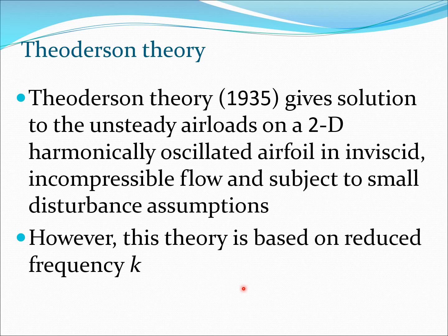Now, Theodorsen's theory is one of the main theories used as far as fixed wing problems are concerned. And this theory gives solution of the unsteady loads for a 2D harmonically oscillated airfoil in inviscid incompressible flow and subject to small disturbance. So this theory is based on reduced frequency K, and this is a very fundamental theory.